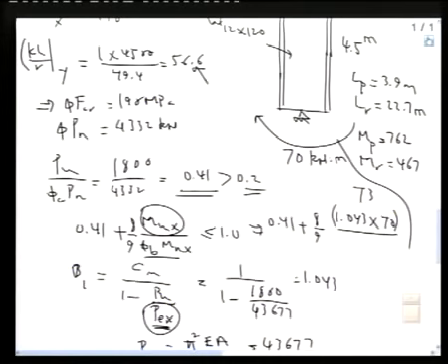From these two, you can find out that phi Mn will be equal to 677, which will be 0.501, less than 1. Okay. Notice I left some few steps for you to be done. Here we have Mb, you have to calculate Zx multiplied by Fy, which is 250, to get the 762, and Mr is 0.7 Fy, which is 250, multiplied by Sx to get this value.